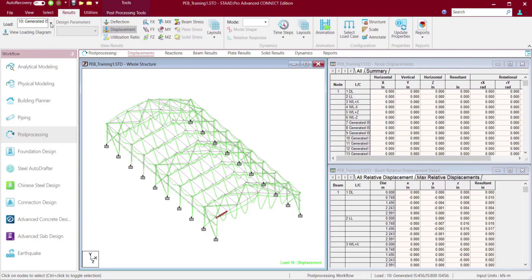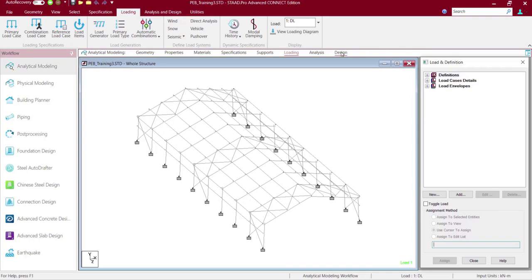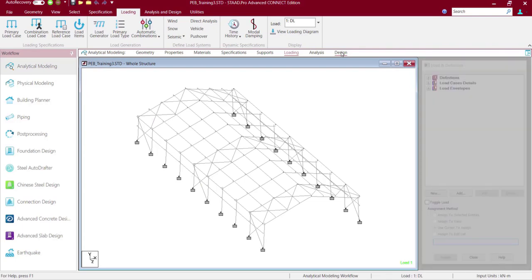But in the previous scenario, that means without the envelope option, you would have to create two different sets of parameters, parameter 1 and parameter 2. For example, in parameter 1, you define the Indian code or AISC code, and within that parameter block, you would have to define different parameters related to the strength check, like UNT, UNB, then FYLD, effective length factors, and so on.